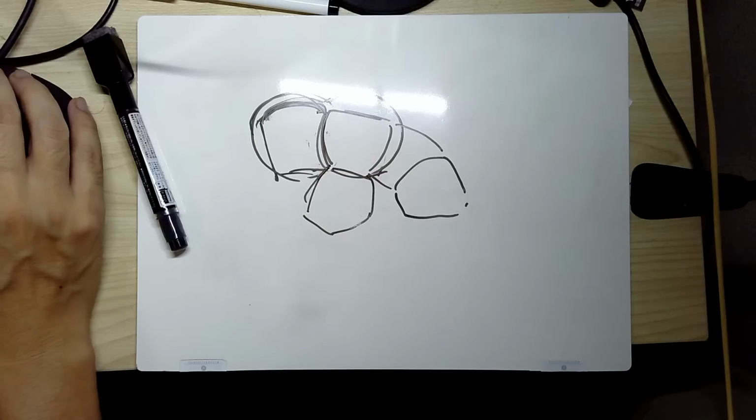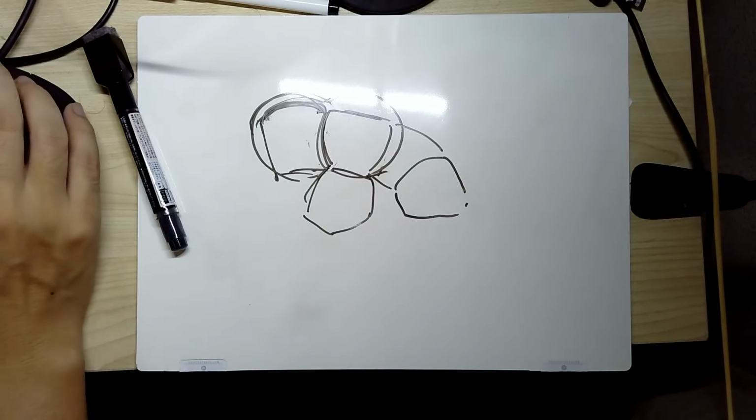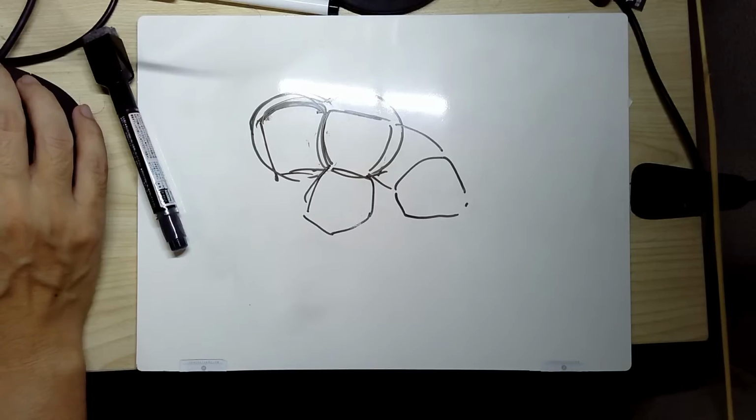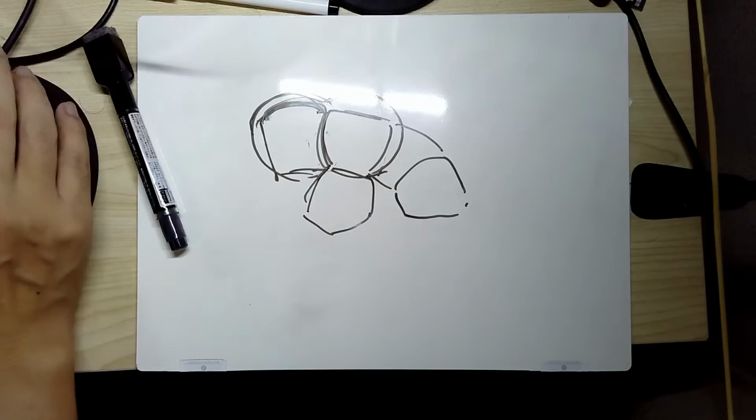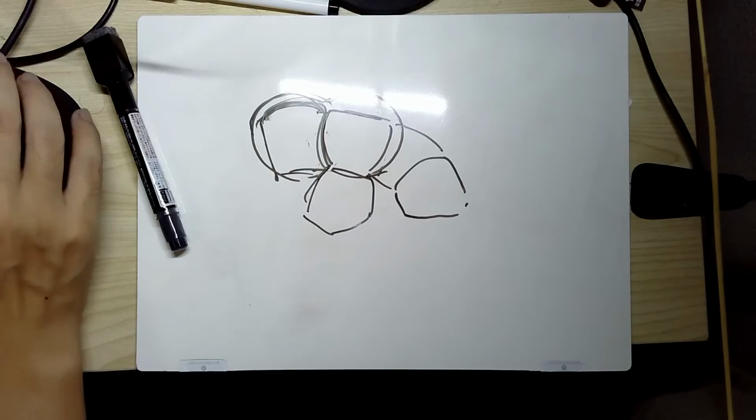So first things first, in order to create the inflation, you need to have a bunch of points on each surface, and currently there are no points inside the surface. So let's try to create that. The point positions and numbers should be shared if you are sharing the wall. So you need the same point numbers and the same point positions for each inner wall if you are sharing the same wall.